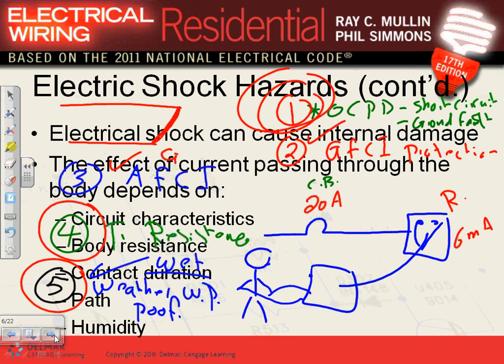The ground fault protection electronics are supposed to look at the current that comes in and the current that comes out. If there's a difference of 6 milliamps or more, it trips. So if the system is grounded, it's okay. If the system is not grounded, it's okay too, as long as you can capture what's coming. The problem with knob and tube is they're sharing neutral, so you have to put it in the right location so you don't get nuisance tripping, because the neutrals, especially if you put a circuit breaker, are coming from all over circuits. I'll show you a couple of diagrams. Any questions, guys, about this?